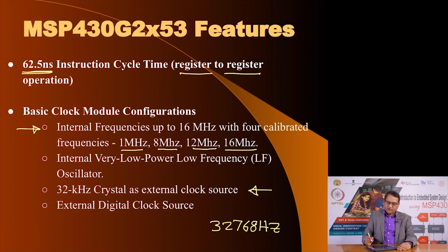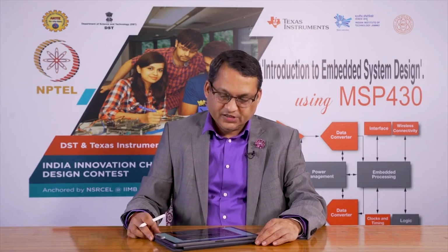This kind of RTC crystal could be used as an external clock source, or you can have an externally generated digital clock source you can apply to the MSP430 as a source of clock which could be internally utilized. And you can change the clock frequency. What we had mentioned, one of the salient features of contemporary microcontrollers, is the ability to scale the clock frequency of operation. MSP430 has that feature.